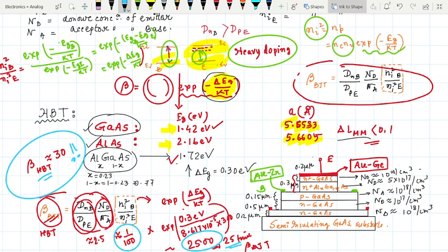So to reduce this we have just considered 1 by 100, but instead we are getting 2500, which is very huge, but we are getting only 30 as the practical value. So there lies some mismatch. We will try to find out what is the cause for this low gain, what factor limits this gain later. So now theoretically we have achieved high current gain, but practically we have not. Some factors limit this and we will discuss it later.